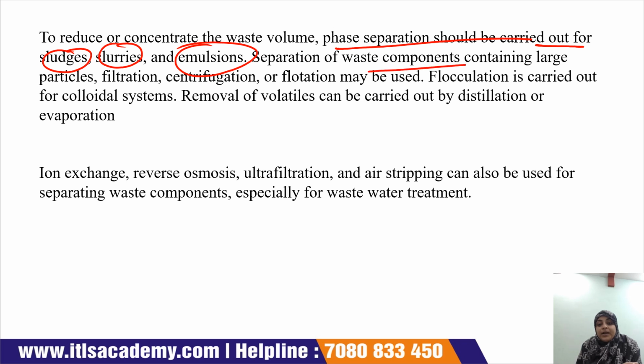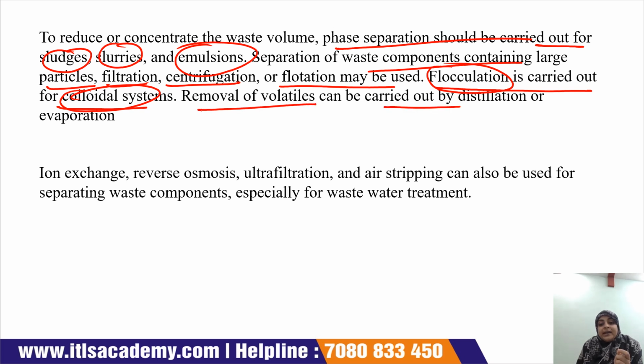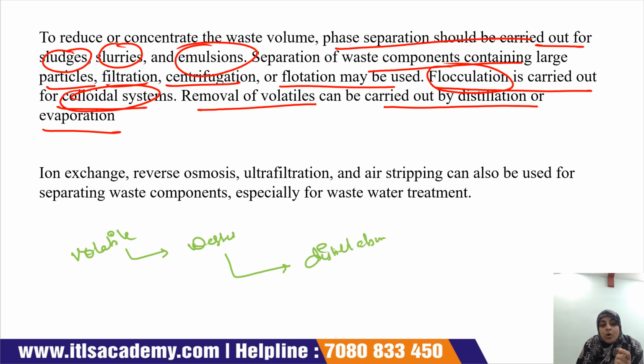For separating waste components containing large particles, filtration, centrifugation, or flotation may be used. Flocculation is carried out for a colloidal system. If there is a colloidal system, then in that case we do flocculation. Removal of volatiles can be carried out by distillation or evaporation. So if there is a volatile compound present in a waste, then it is removed by either distillation or evaporation.